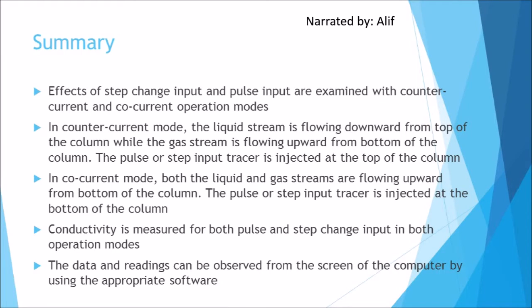In this experiment, the effects of step change input and fast input are examined. The operation modes for both inputs are countercurrent and co-current mode. In countercurrent mode, the liquid stream is flowing downward from the top of the column, while the gas stream is flowing upward from the bottom of the column. The pulse or step input tracer is injected at the top of the column. In co-current mode, both the liquid and gas streams are flowing upward from the bottom of the column. The pulse or step input tracer is injected at the bottom of the column.